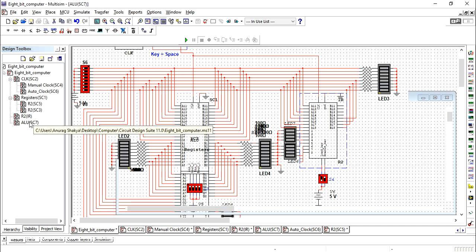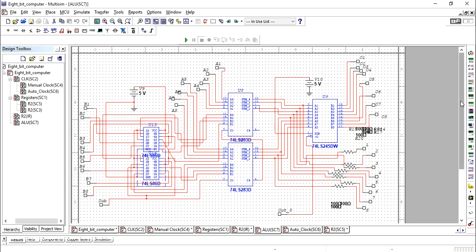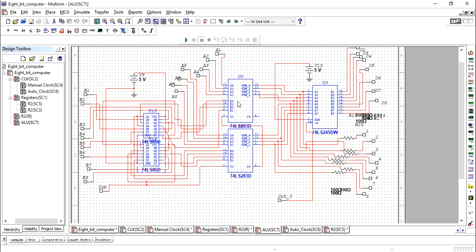The circuit for the ALU I have designed here using just one adder, and using the same adder we can subtract two numbers as well. I take the first complement of that number, then add 1, which gives the two's complement, and then add it. So this adder can work as a subtractor also. This is the signal to subtract. Suppose I want to subtract one number from another, then I have to enable the subtract signal, and this is a buffer to control the output. For that I have to enable this out bar signal.